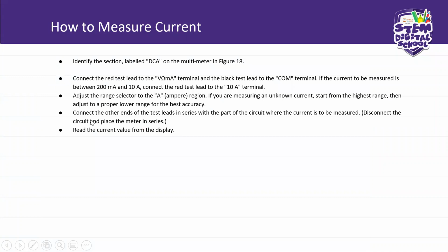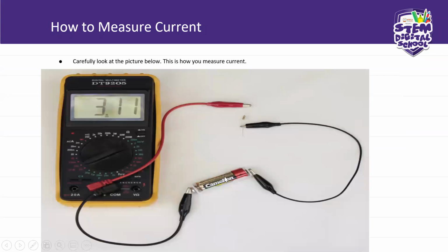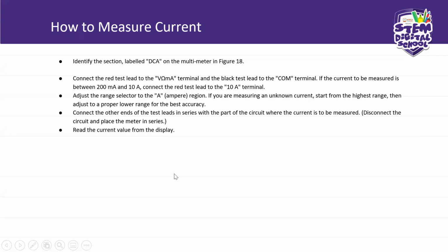Right. And then read the current value from the display. Now, when you measure current, as I said, you remember, the leads must be in series.